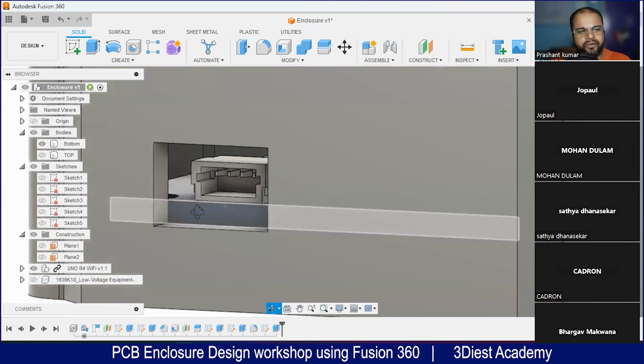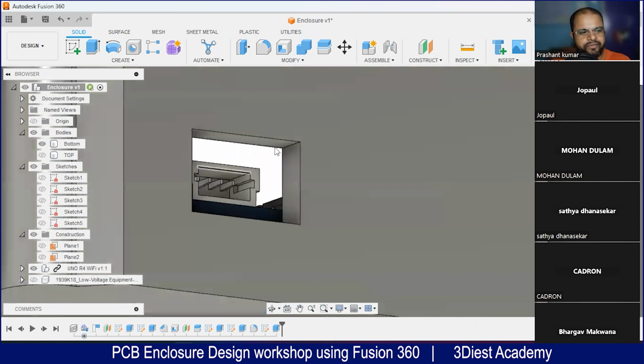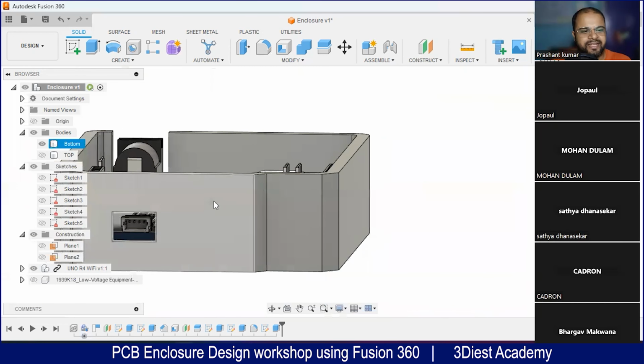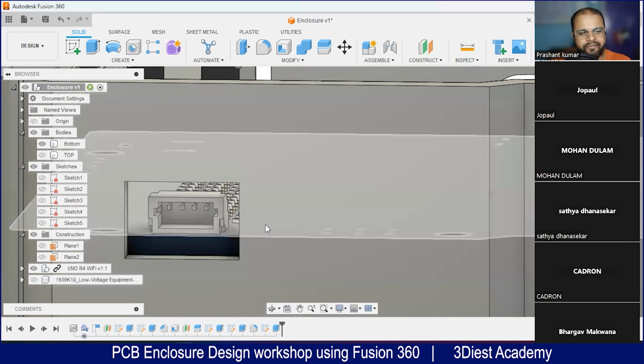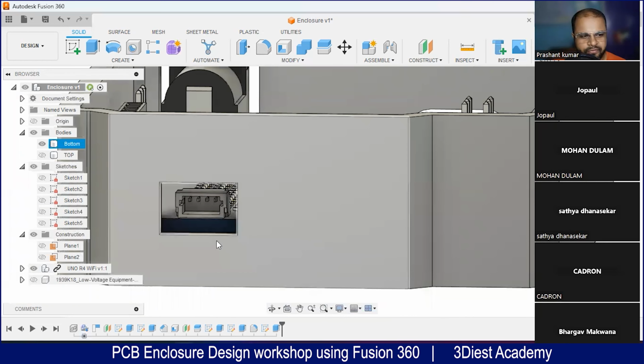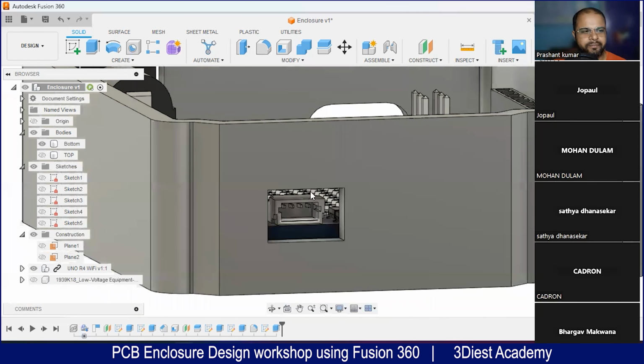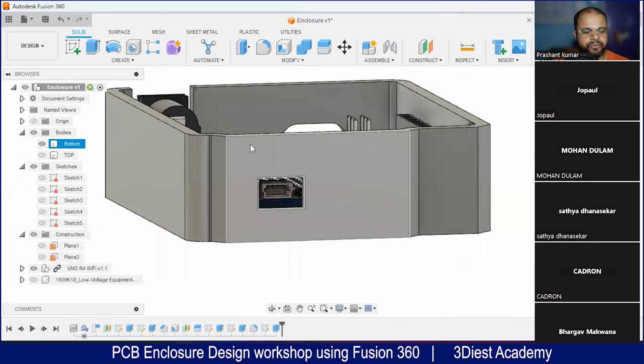I don't know what is the male plug that is going to fit over here, but we had already considered some extra material around that. That's why if things come over here, it will fit correctly. Otherwise, if you want to make it perfectly correct, all the time ask for the connector names with your clients as well. So just mark these connectors onto the board file.